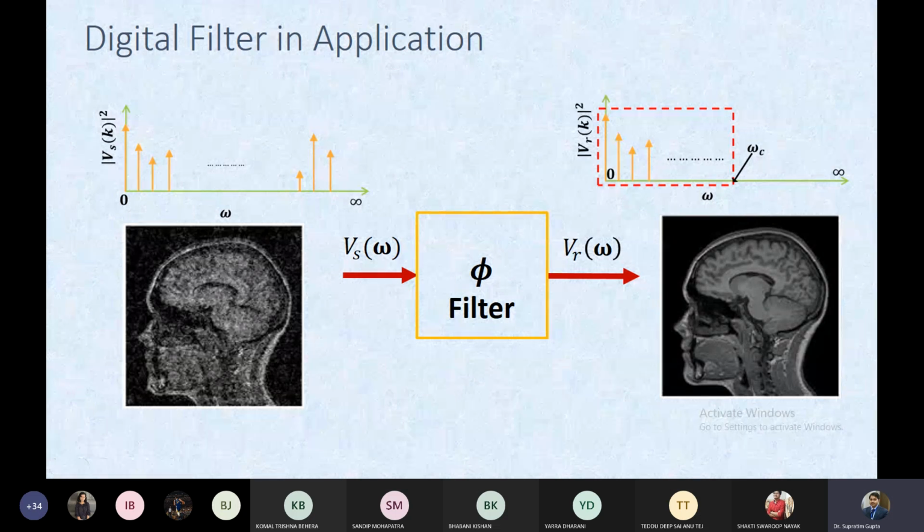Very often we call this term frequencies, but by that we always mean sinusoidal frequencies. But it is not mandatory that we should always take this to be a sinusoid. It can be a square wave also, and that can also have a frequency of oscillation, and that can also be taken as a basis, or the unit vectors, unit functions you can say. Basis functions we call them. So this is not mandatory, but for convenience and conventional thinking, we will always be specifying the sinusoidal frequencies here.